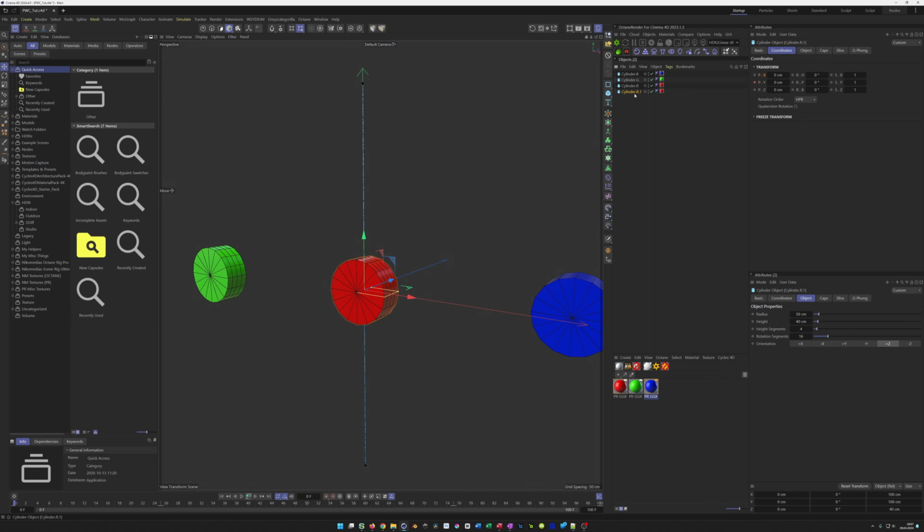Don't forget, in this copy, we don't need this keyframe. Don't forget to delete it, because this one we use as a linkage here, and this would then go up with this one, but at double the speed, and so this is not what we need. So delete here the keyframe.